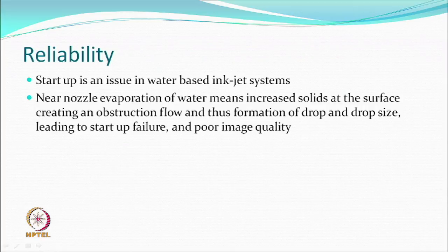So, all they are related. So, if you have a startup issue, that means ink is drying up at the nozzle. Other than, of course, you can have precipitation, coagulation of the dispersion breaking, that is a separate story, then things will be very different.